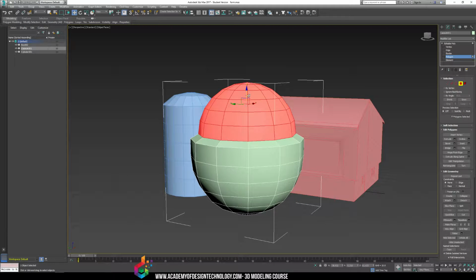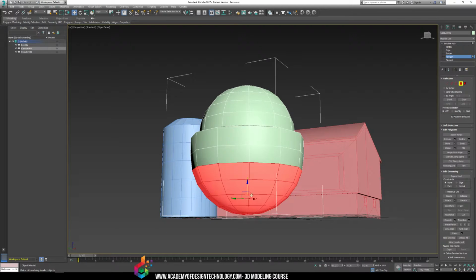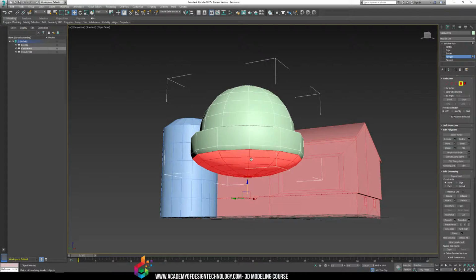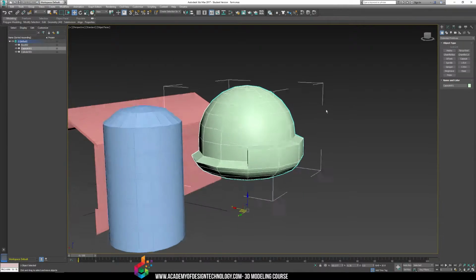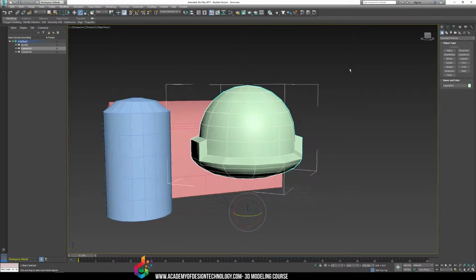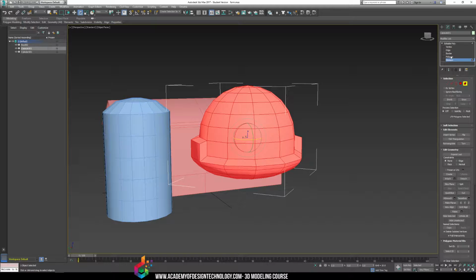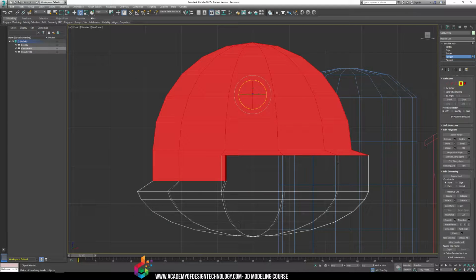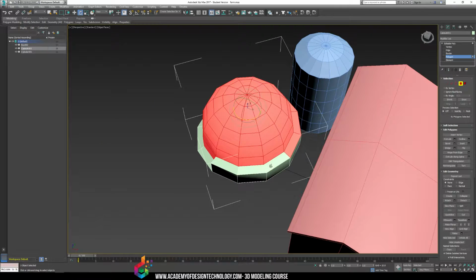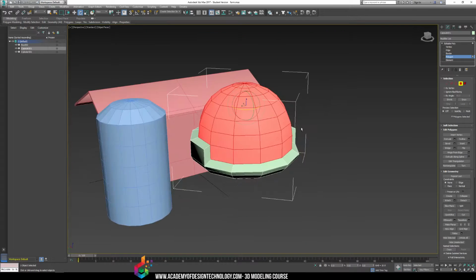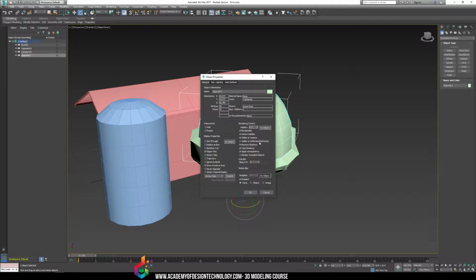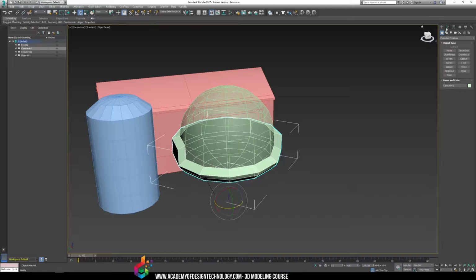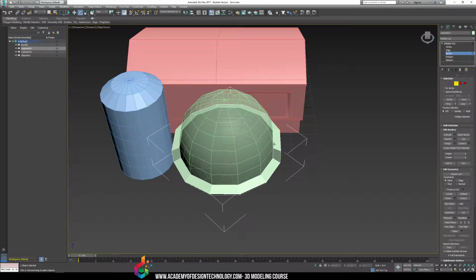So I'm going to extrude this inward like that. A simple UFO type ship right there. And if I rotate that around, I get a very unique shape. And this could be my dome. Here, I'll go to my front view. You see how I just turned this object into a new type of UFO. It's as simple as playing around with the same tools that I taught you. Extrude. I'm going to detach this dome here. Detach there. And I'm going to change the dome transparency to, let's say, 4. Border.